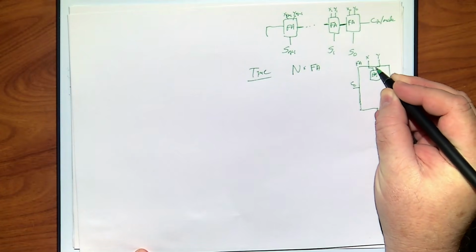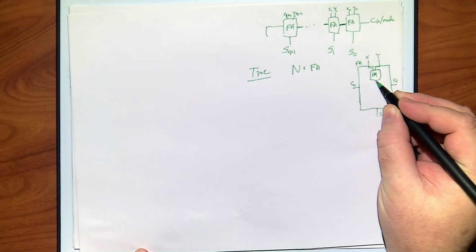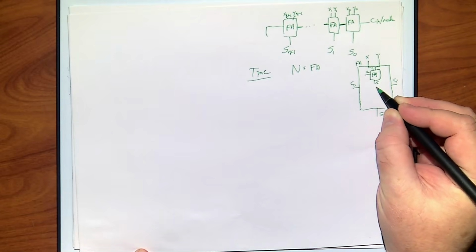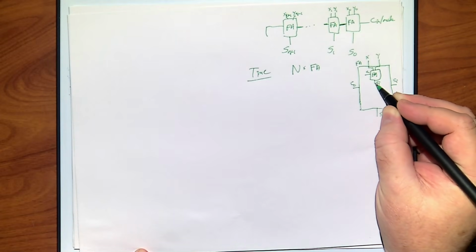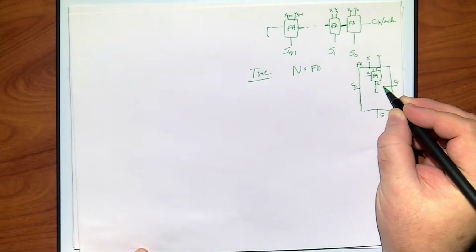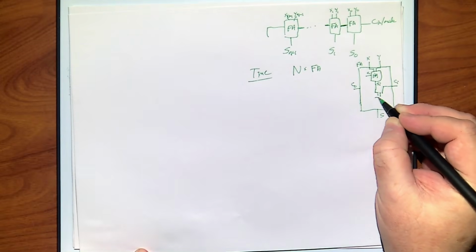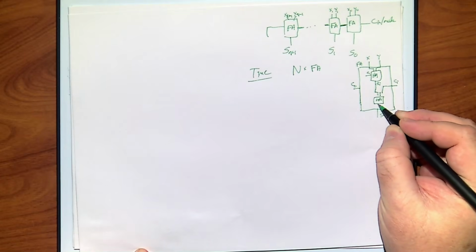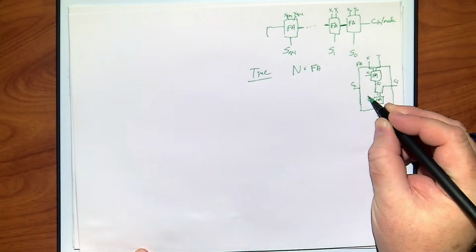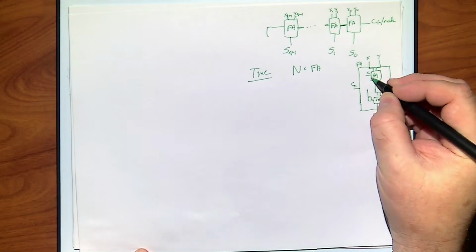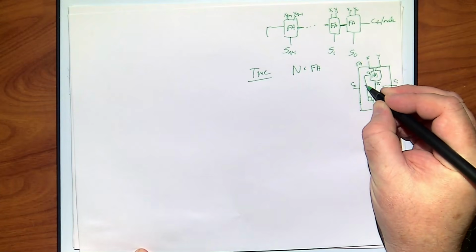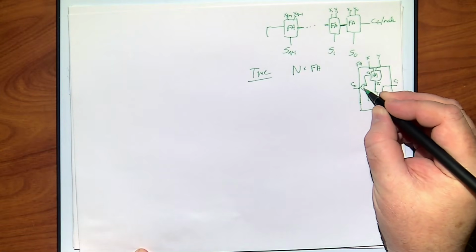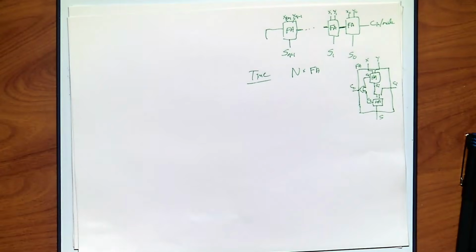We're going to have this little half adder in here. It's going to give me a sum and a carry. This is internal, all right? So I'm going to put sum internal. And then I can take that sum bit and the carry and put it into another half adder. And its sum bit goes all the way out. And then I've got these two carries, carry two, carry one. And then I can either exclusive-or or or these, whatever makes you happy, to get your output. Does that make sense?